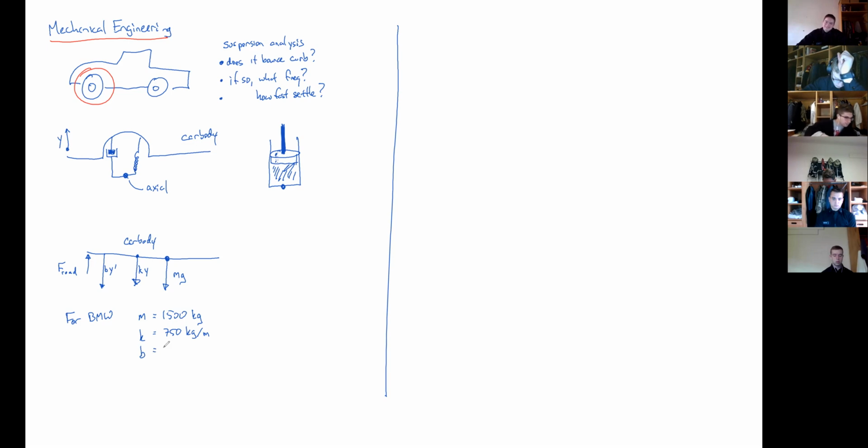The typical dashpot coefficient is about 750 kilograms now per meter per second. So for every meter per second it's being pulled out, it resists that motion by about 750 kilograms. You could do the same thing: put up a video camera, attach the weight to the dashpot, and let go, and it would slowly go down. With a video camera, you could see between two frames it moves 6 centimeters. You know your video rate is 25 frames per second, and you could divide back out. And then gravity is a constant, 9.8 meters per second squared.